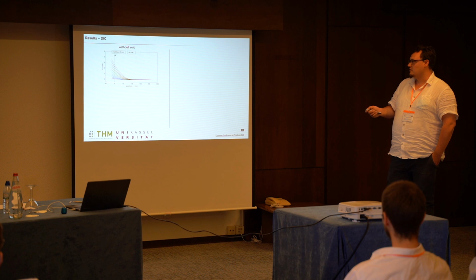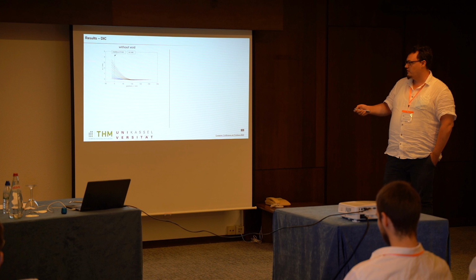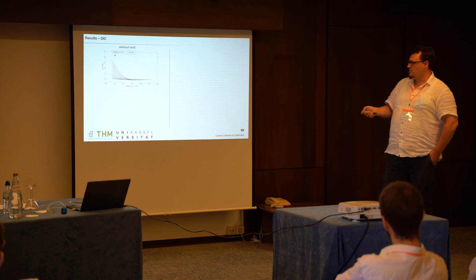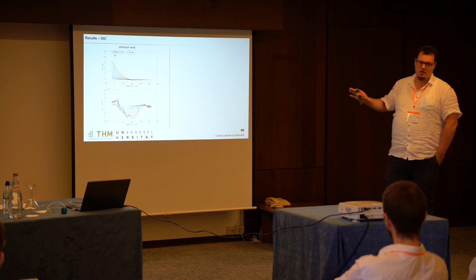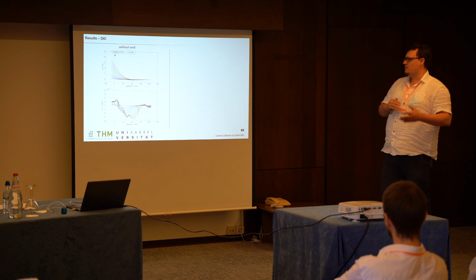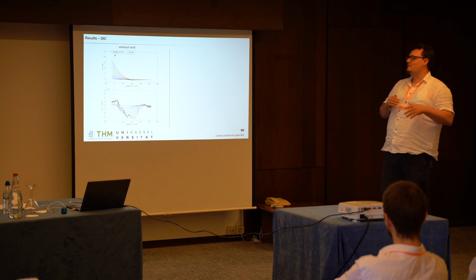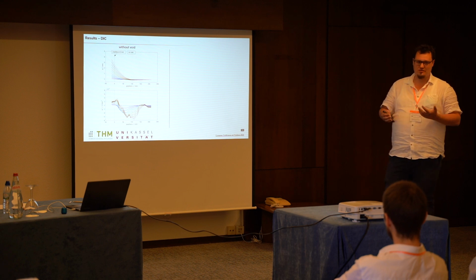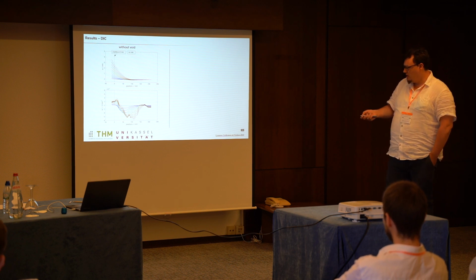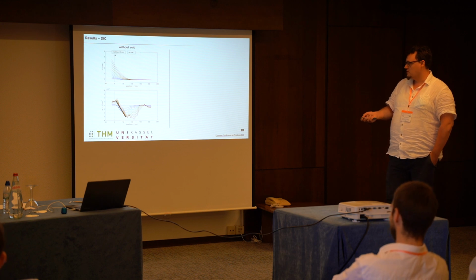Now, results for the DIC measurement. Here on the top you see the deflection curve, w, plotted over the position. Here in front, the dotted line shows also the crack tip. And here we have to differentiate three times, and this differentiation leads to an increase of the numerical noise. It's not so easy. You also see here no constant value.